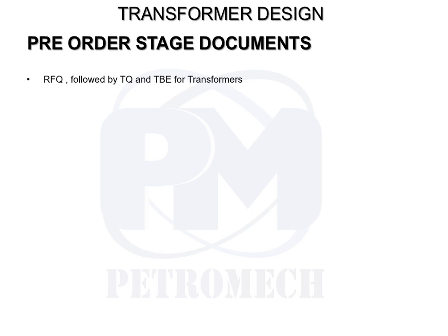It's always fruitful and better that we close all the open points in the pre-order stage itself, so that the vendor doesn't get room to play post-order with any data or parameter which may have significant impact on our transformer design. That has to be ensured by the design engineer in the offer stage itself.